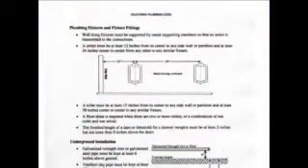Ejectors must have a backwater or swing check valve and a gate or ball valve installed in the discharge line. The gate or ball valve must be downstream from the backwater or swing check valve. Highlight that.